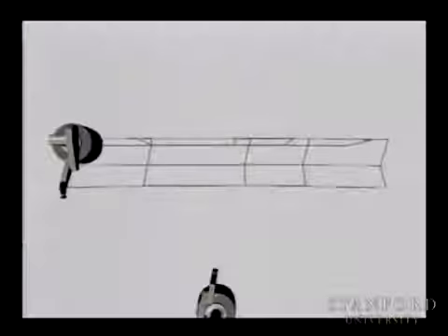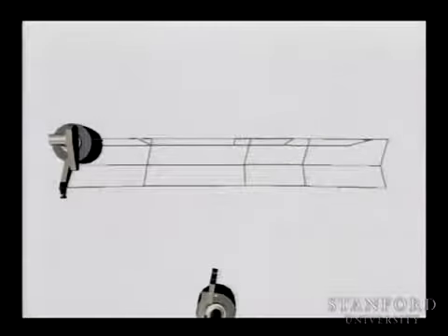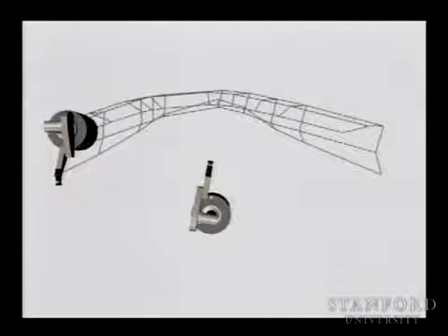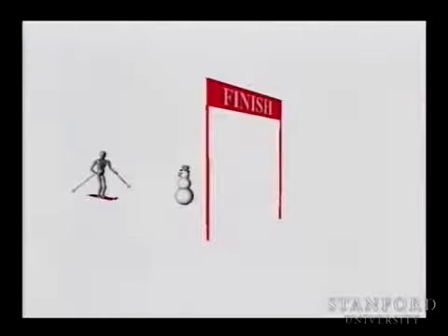We are creating artificially those forces and making the robot move away. But if you have a global plan, you need to deal with the full plan so that you will not reach a local minima. And we then apply this technique to modify all the intermediate configurations so that a robot like this would be moving to a goal position through this plan.